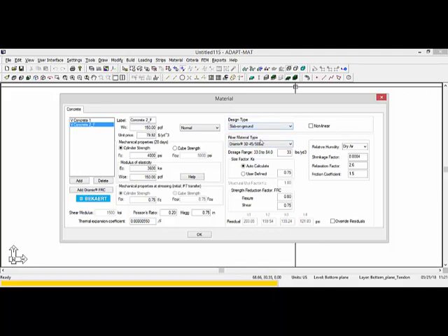So if we go to fiber material type and use the pull down menu, we can now see the list of fiber types that are produced for this type of design. We'll go ahead and select the Dramix 4D 65/60 BL fiber. And when we select the fiber type, we then get a sorted dosage range that we can apply. In this case, the dosage range is 33 to 67 pounds per cubic yard. These are the dosages that can be applicable to this fiber type for this type of design.